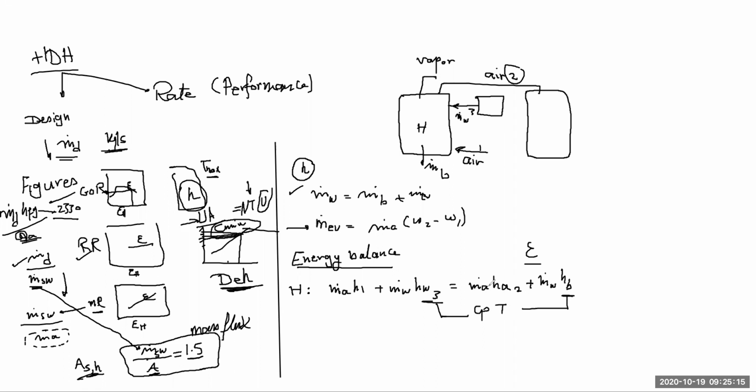It is not very accurate because Cp times temperature has been basically created for a difference of energy, like delta H, for example, is m dot Cp delta T. But the expression of Cp times temperature can approximately be accepted as a way to represent the energy of the water, provided that you are sitting in an exam and you don't have software or a table where you put the value of the temperature and it gives you the enthalpy or vice versa.